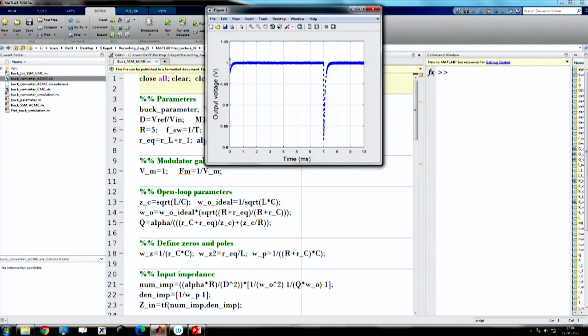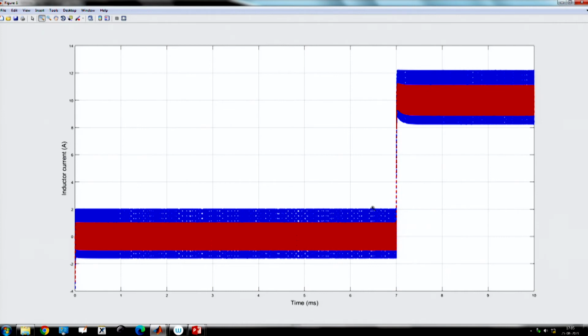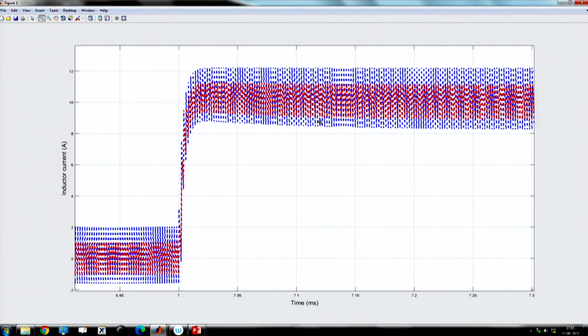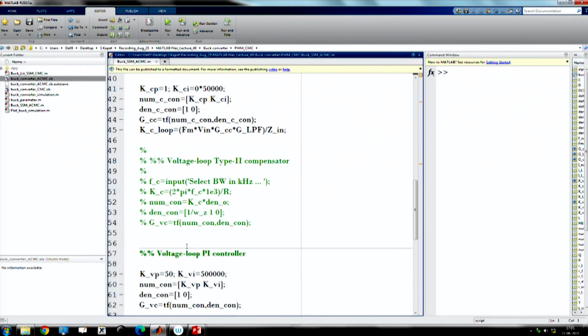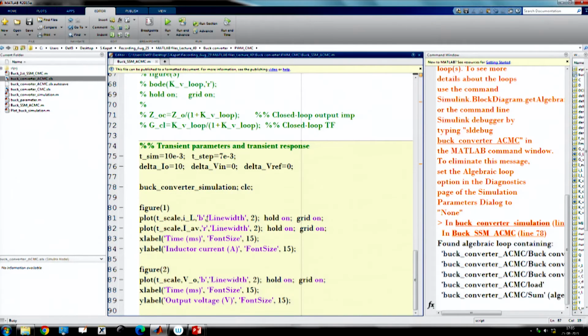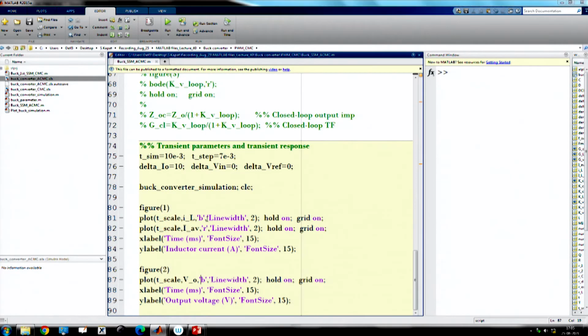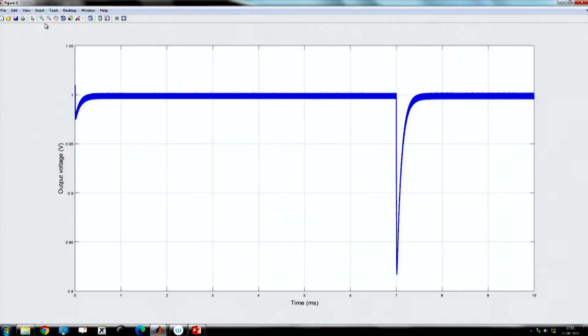So, that means by doing that we can ensure more or less stable behavior. We can achieve the stable periodic behavior. That means if we go to the solid line, that means what we need to do, if the current loop bandwidth is slower, we have to slow down the voltage loop bandwidth, and also we may have to add the ramp, because otherwise...